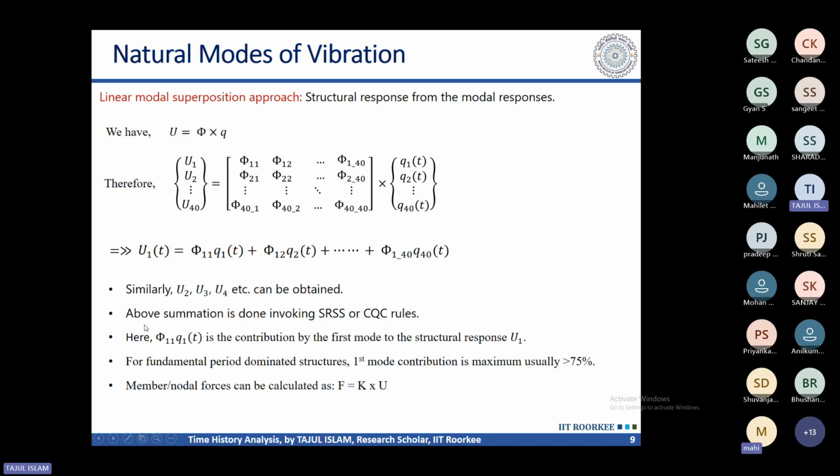This addition is actually not a straightforward addition. It is an SRSS rule or CQC rule. If you do not understand this, we can have a separate session to understand these rules, along with how to calculate the response in modal analysis manually. That also we can take up if people are interested.